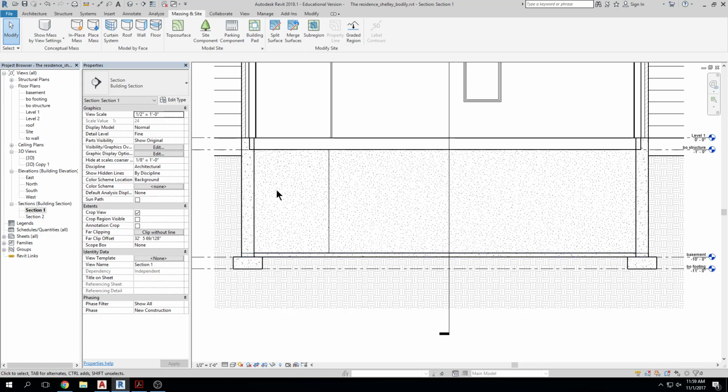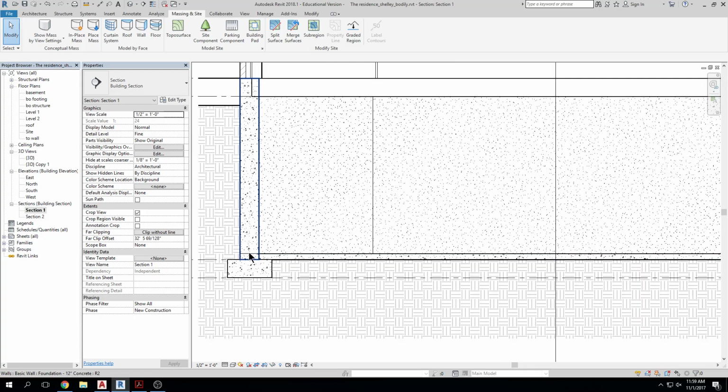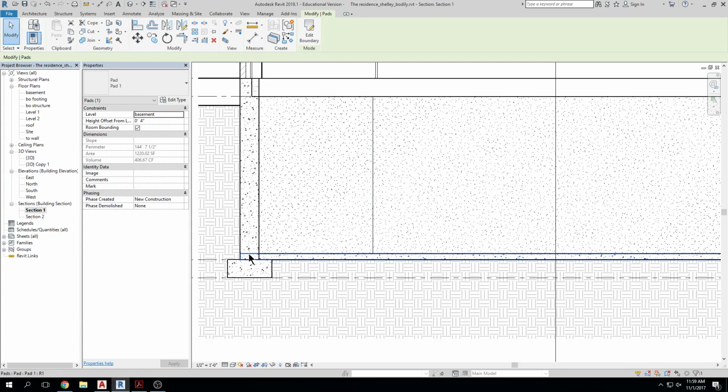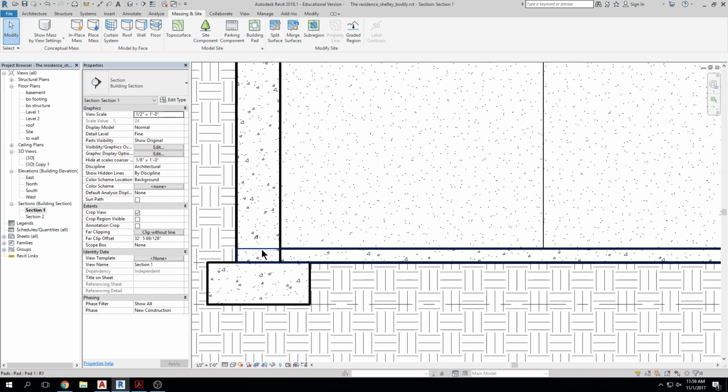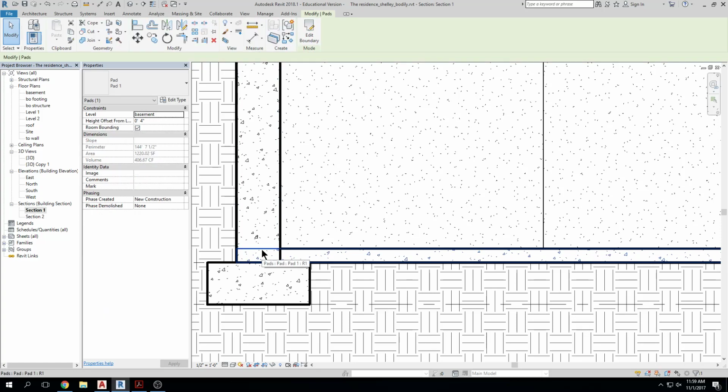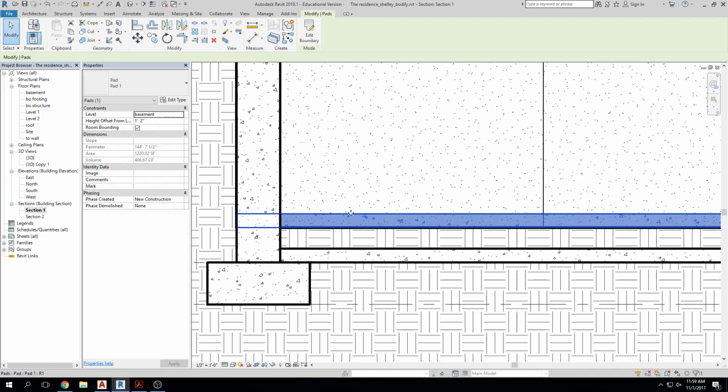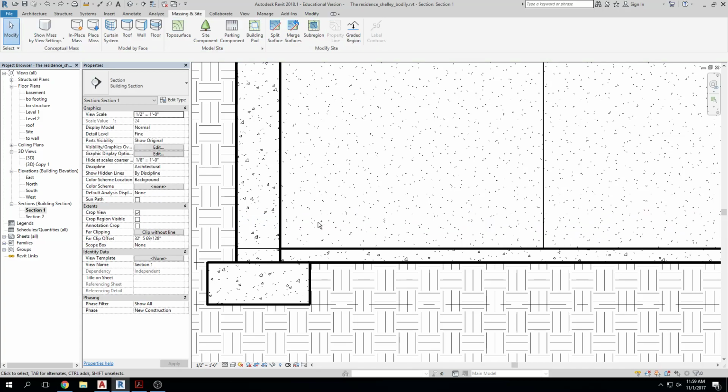Oh, okay. Yeah. So my building pad is showing up below the floor. Move it. Yep, drag it up. So first thing, if you click on it and look at it, make sure it is on the appropriate level. And if you need to move it up or down a little bit, I'm going to tab and select it. MV is move, and I'm just going to move it if it needs to be adjusted a little bit. I'm not very worried about moving the building pad up and down because it will generally stay in place, and it's not a building element that I need to worry about.